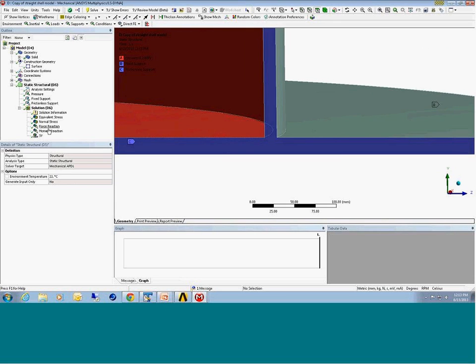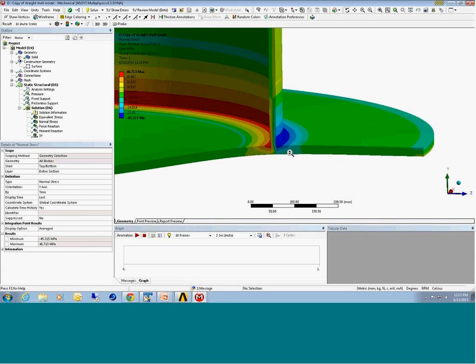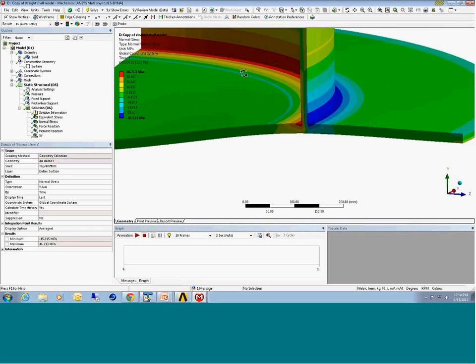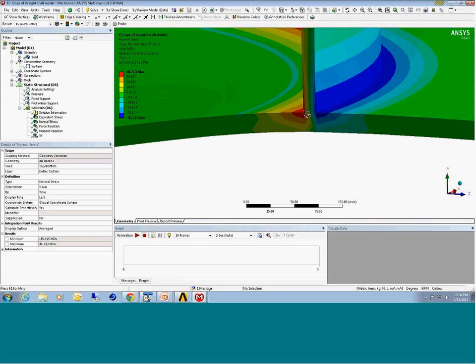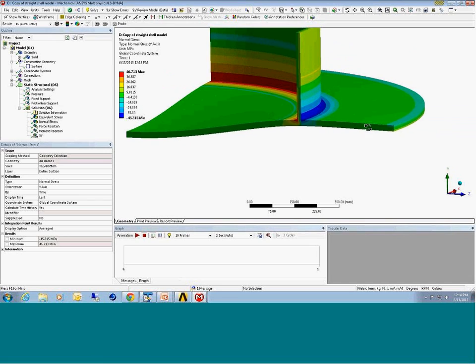Now, I could use ANSYS to calculate the vertical stress in the y direction, just pull it off in the standard procedure of taking the average stress through that profile. And the average stress would give me a peak stress at that intersection, but it's a sharp corner, and it's actually averaging stresses from the vertical plate and the horizontal plate. So not necessarily a very realistic data point to use.